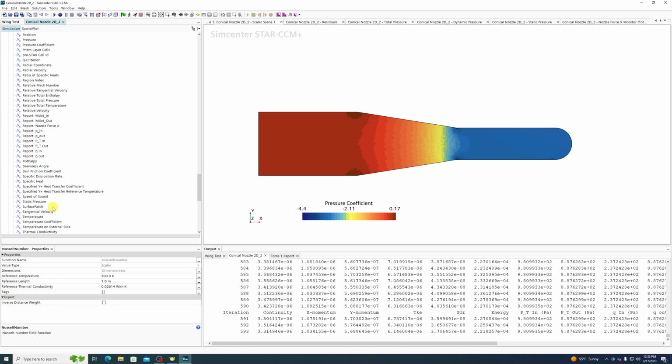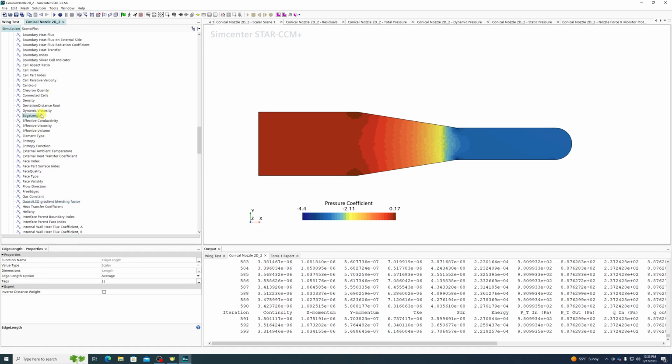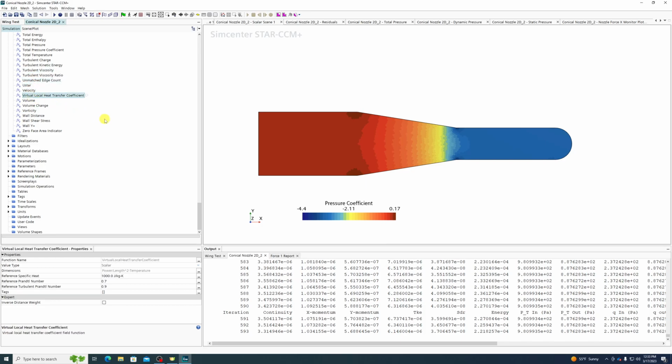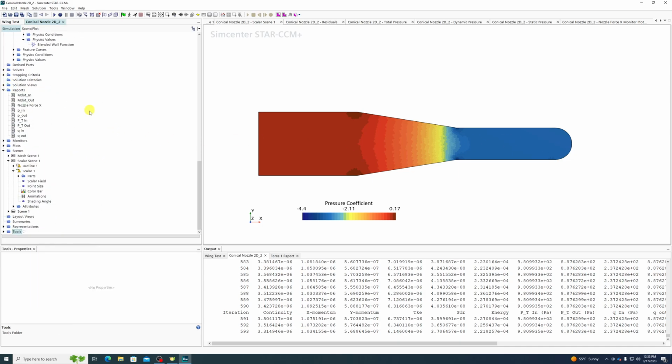Doesn't particularly look like it. You can make your own if you wanted to, but again, some of these, especially things that are supposed to be dimensionless, not just include the word coefficient, those can have values that you need to tweak down here under field functions. If you're not dealing with that, don't worry about it too much. But it can potentially matter if you're doing things like trying to look at pressure coefficient, because if you do that and don't change these, your values are probably gibberish.